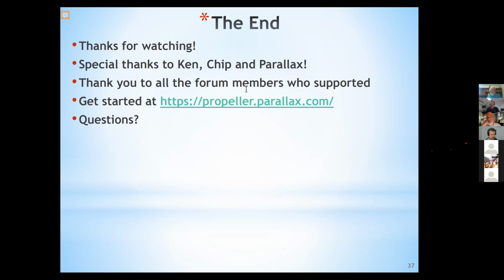I think there was a SPI interface where the Raspberry Pi was the master, but even though the P2 was a slave, I wrote code for the Raspberry Pi that took commands from the Propeller 2. So either way you want to do it, you can have the P2 be in charge and tell the Pi what to do, or you can have the Pi in charge and tell the P2 what to do over that SPI interface. And you could, of course, tell it to capture images from the camera and do whatever you want to do with them. So I'm pretty sure that can work.